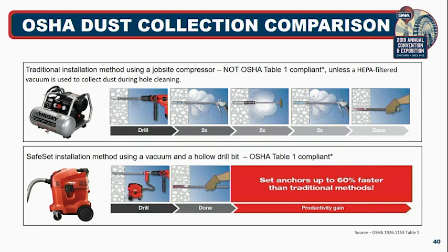And these vacuum systems actually serve an additional purpose in that you guys might be familiar with the new OSHA silica dust standard that's out in the market right now. It was implemented last year, and basically what that entails is OSHA regulates that there's only a certain amount of particulates that can be released out to the air during the construction processes. They measure, they check, and you could get heavily fined if you fail to meet that criteria.